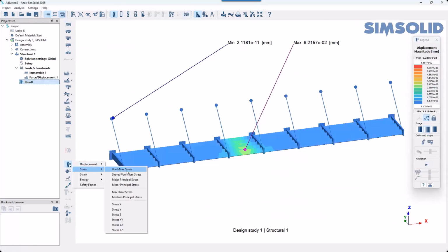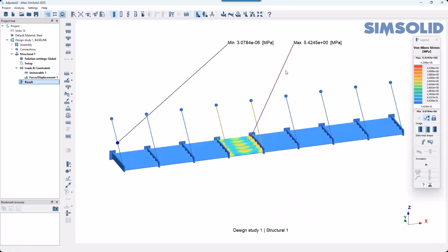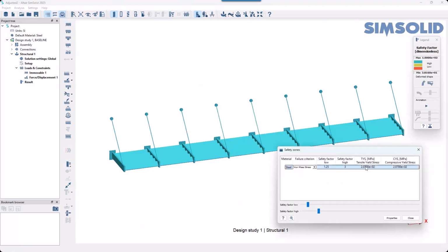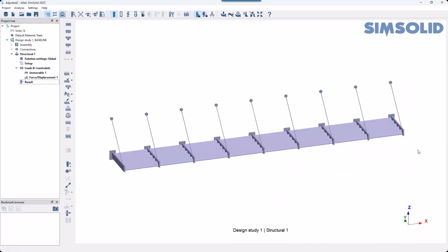So you can see the displacement is quite low in this example, obviously based off of the input loads that I defined. I can also look at my stresses, so I can see how much stress I'm getting in different parts of the model. And again, it's quite low. So perhaps the loads I've applied didn't really stress this to any significant limit. But if they were getting close to some sort of threshold, we could also set up a safety factor where we can consider anything within this tensile yield stress range with a safety factor defined as a high and low threshold, and we can display that. Now in this scenario, I'm well below my safety thresholds anyway, so it's not going to really factor in. But we could certainly look at how this might display if we had a higher stress structure.